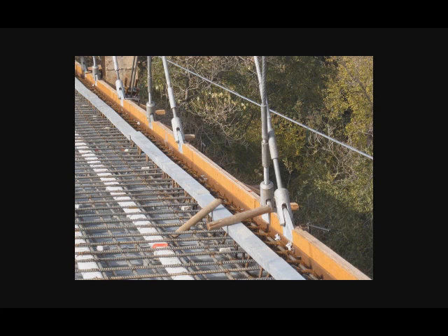So that's one line of defense for our tie force. But in this case, the deck is integral with the tie, and so we have multiple levels of load path. You can see in white the post-tensioning tendons that run through the deck. They keep the deck in compression even when it acts as a tie girder, and it also serves as a backup load path in case we lose the tie.